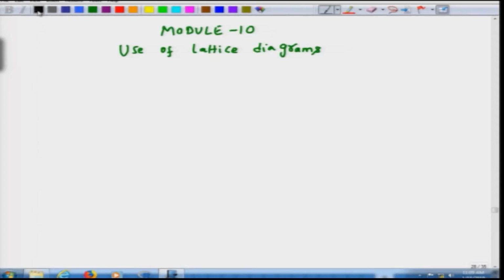Okay. So, we have already seen the basic idea behind the lattice diagram. It is to essentially start off at one end and then to trace what happens to the voltage that is launched, appropriately reflecting off at the load as well as at the source or the generator ends, right. So, let us take a couple of examples. I will show you how to use these lattice diagrams using multiple examples, so as to bring out certain special characteristics of this time domain approach.